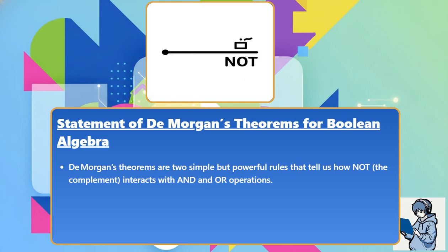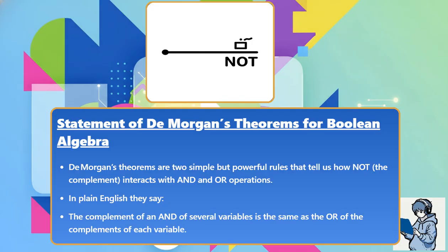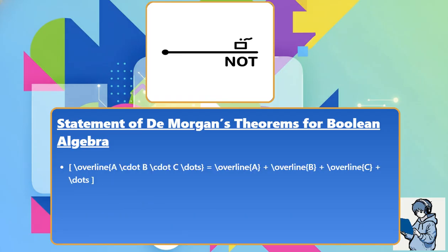De Morgan's theorems are two simple but powerful rules that tell us how NOT, the complement, interacts with AND and OR operations. In plain English, they say: the complement of an AND of several variables is the same as the OR of the complements of each variable. NOT(A·B·C·...) = (NOT A) + (NOT B) + (NOT C) + ...